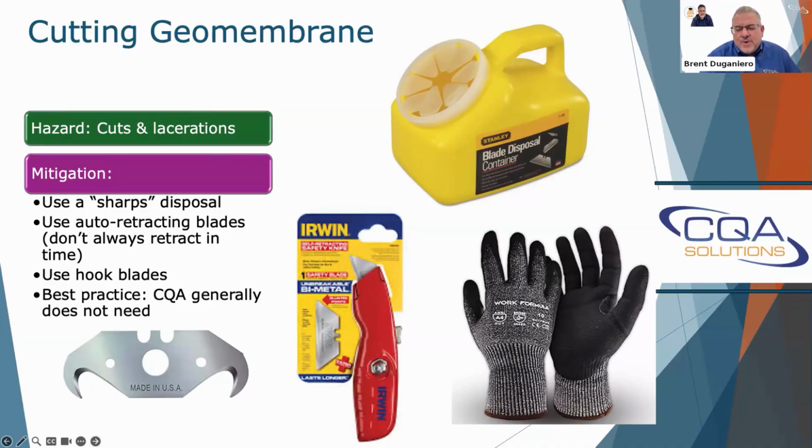And finally, one thing that we recommend, both for quality and for safety, is that you have some sort of sharps disposal on the geosynthetics. Make sure it's being used for any disposed blades, but also when we're stitching geotextile, you've got needles that might break. You should have a safe place to put them so we don't wind up either injuring ourselves or damaging the geosynthetics.